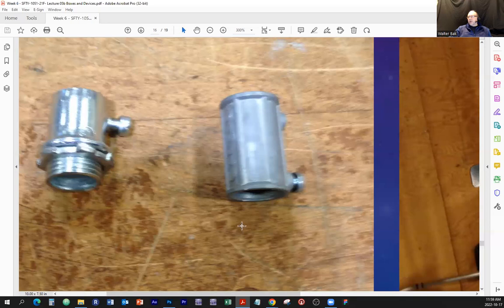And one thing I'm going to point out to you is this is not meant to hold weight. It's just to hold those things in place so they look nice, rigid, and presentable, and provide a clear way. The EMT, if it's on the wall, should be mounted using fasteners, the holding devices. It'll just look like little hooks, and then just grab it and hold that against the wall, for example, or against the timber framing.